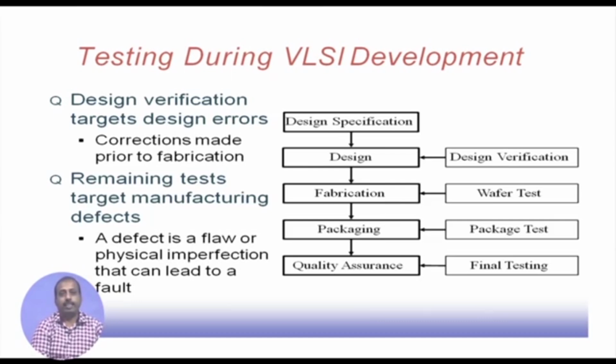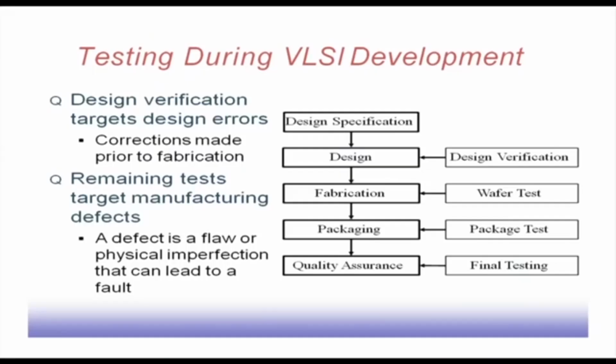Now, what is the guarantee that this design that I have got, consisting of flip flops and these gates, really has the behavior of the specification of the counter that I had? This is actually done by the verification process. If there is a design error, then this verification process will try to prove some properties of the specification on this design, and if the design is incorrect, then those proofs will fail.